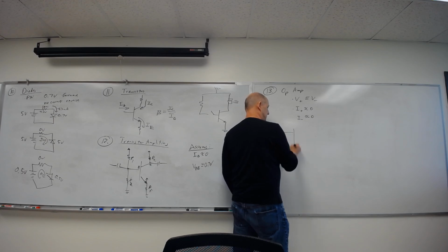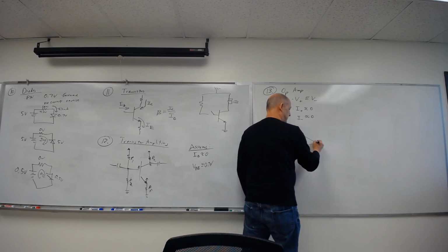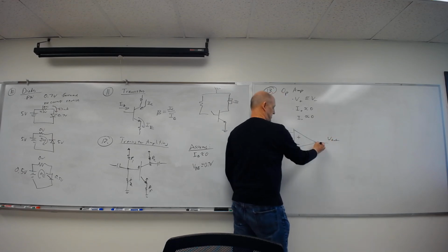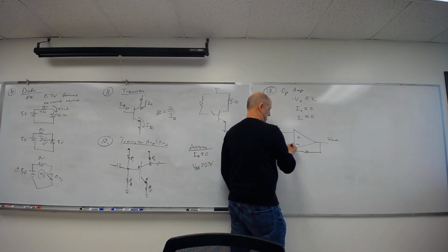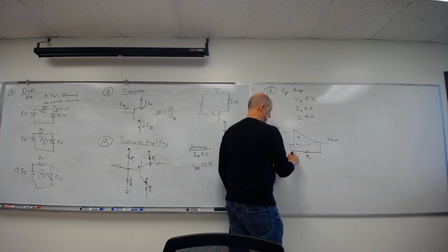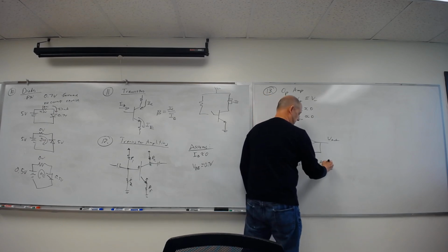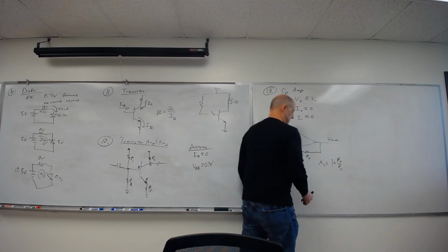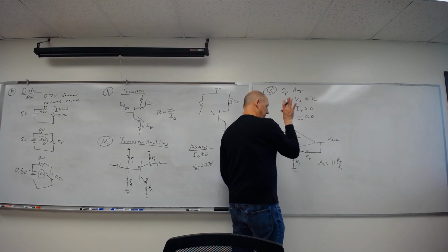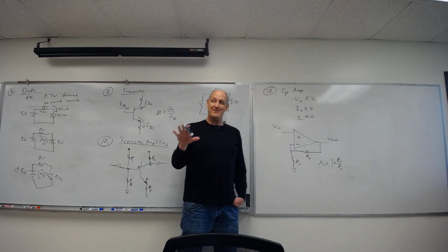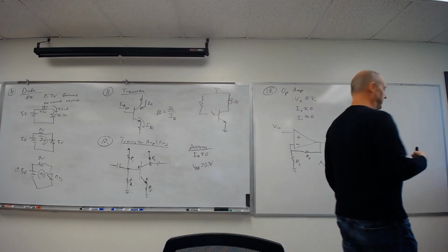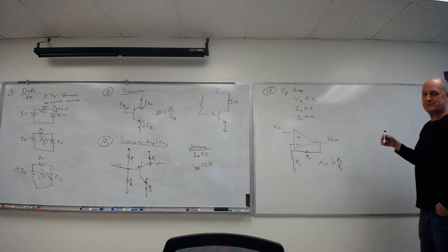And then we used those and did this last week in class. You can go back and look at it. And we solved if I have a non-inverting op amp, there's the feedback resistor. There's the ground resistor. It has a gain. What was the gain? It's 1 plus the feedback over the ground. You should be able to find all the voltages and all the currents on here, just like I did in those detailed examples in class. Hopefully you did last week's homework and lab and got it already, so you're up to speed on this stuff.